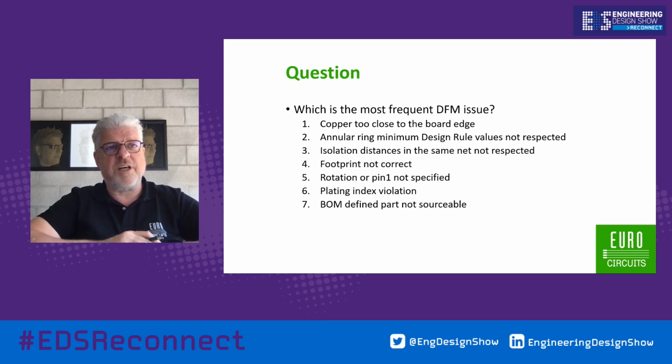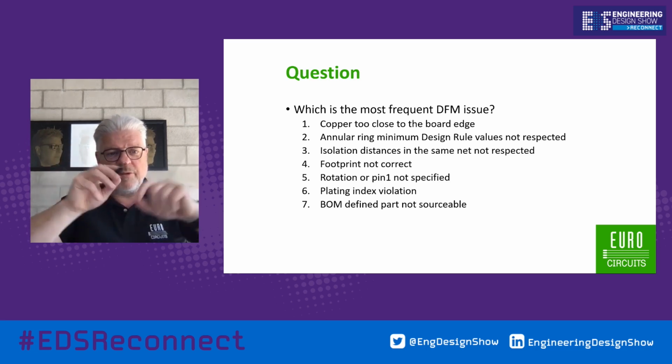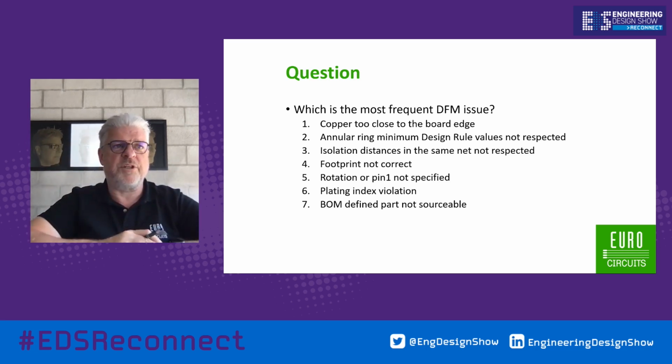Isolation distances in the same net not respected, as I showed you before, between the holes that were too close to each other. Footprint not correct. Daily stuff, multiple times a day. Rotation or pin 1 not specified. Daily stuff, multiple times a day.